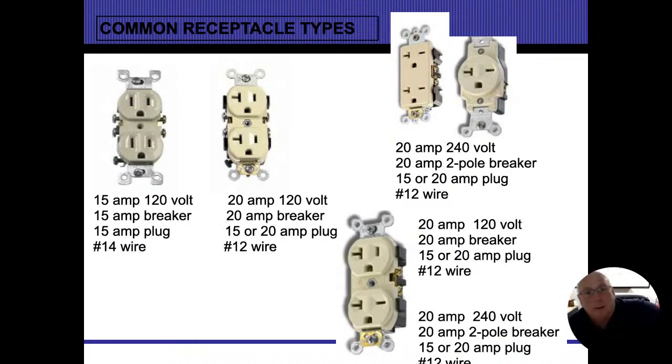A little bit more on outlets here. You should have a rough idea of which slot is which, which screw is which, and how many amps each one is designed for. The first one on the left, we can see both slots go straight up and down. We do have the round cave-like one, and that is going to be my ground slot. So the green screw on the bottom left, both of those ground ports go to that green screw. It also goes to those metal tabs at the top and the bottom, and the screws in the top and the bottom. Those are all tied into the ground system for that particular outlet.